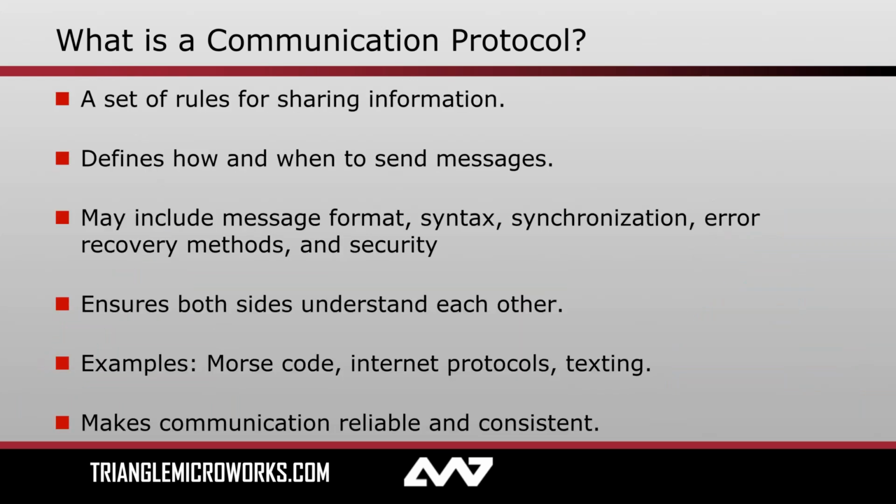So to recap, what is a communication protocol? Well, fundamentally, it's just a set of rules for sharing information. It defines how and when we share that information, and it includes a lot of other stuff besides just how to decode letters from smoke signals. It might have message format, syntax, synchronization, so that I know, hey, don't send messages while I'm sending, for example, if I'm not able to have a full duplex system. Error recovery and even security might all be rolled up and wrapped into a communication protocol. And fundamentally, we're doing all of this to ensure that both sides can understand what the other one is saying.